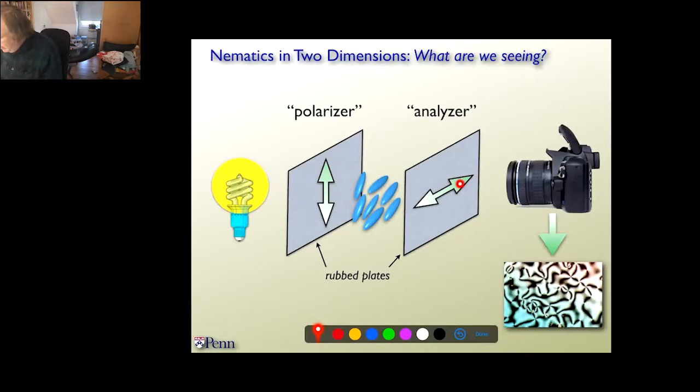But in between these two plates is some liquid crystal, and these liquid crystal molecules are long molecules. They have an anisotropy that is both geometric and optical. Because of the optical anisotropy, when you send polarized light in, it hits the molecules and gets rotated a little bit. It becomes elliptically polarized, and so you actually get a signal out. That's what you see down here. You see the light. And then you say, why do you see black? I thought you said that there was always a signal.